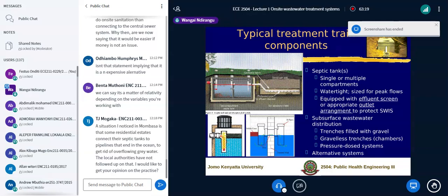And it has two reasons. First of all, as water comes in here, it has a bit of speed, a bit of velocity, a bit of energy. Velocity gives water energy. So this means that the velocity is dissipated by introducing the water into the chamber, and therefore does not disturb the rest of the system.